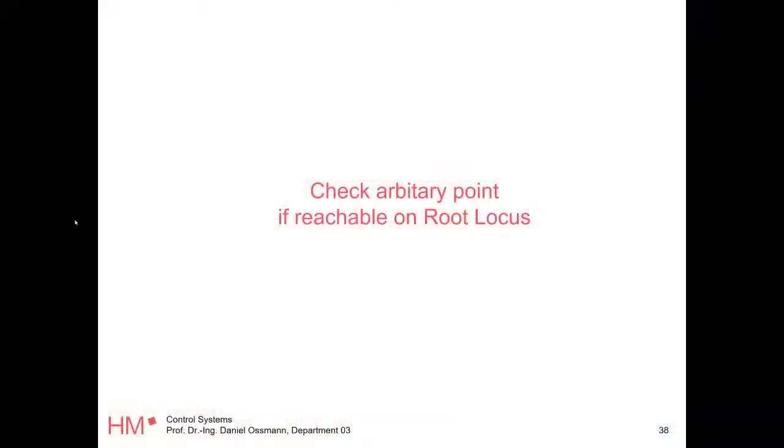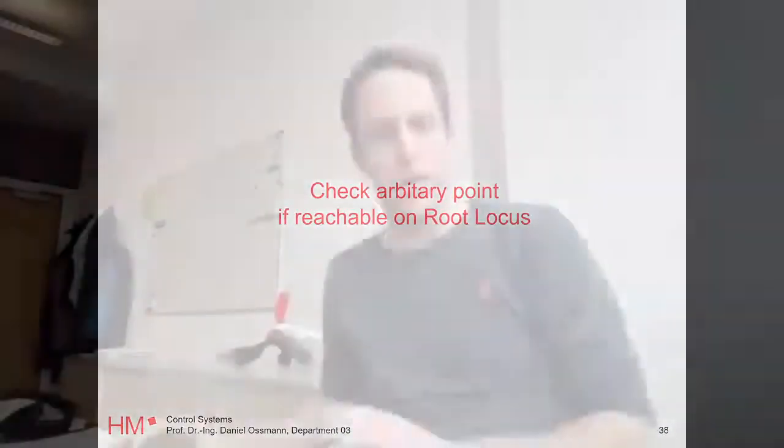But that's no problem, because we can add dynamics to our controller and thereby move the root locus curve around. And how are we going to do this? This is what we are going to develop next. Okay, but step by step. So before that, let me give you the big picture here. The goal is to design controllers and make our root locus curve go through the desired point, right?